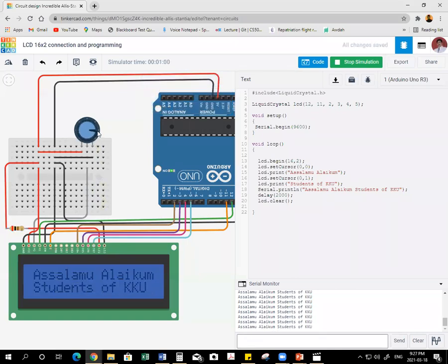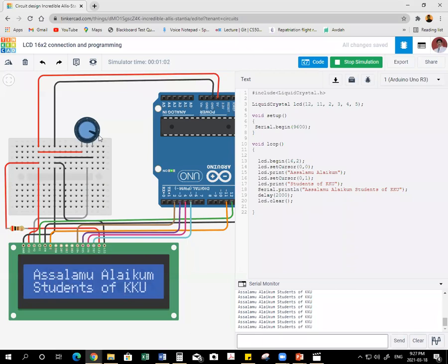Now if I change the potentiometer, we can have the optimum, because brightness and backlight should go together to get the exact intensity of the LCD, right? You can see in mobiles also, same thing. If you are in power saving mode, the backlight decreases. And if you increase the brightness, it will also decrease the visibility. So these are the two factors which affect the visibility of any display. So this is very important.